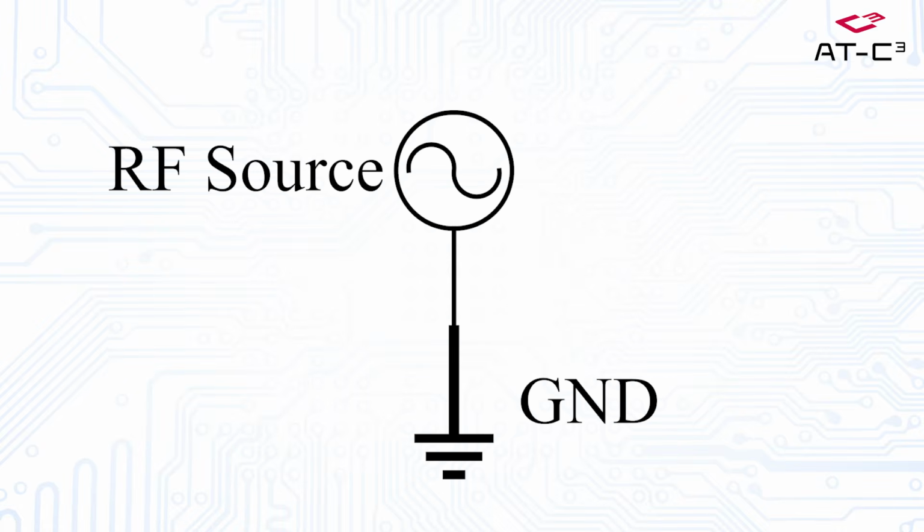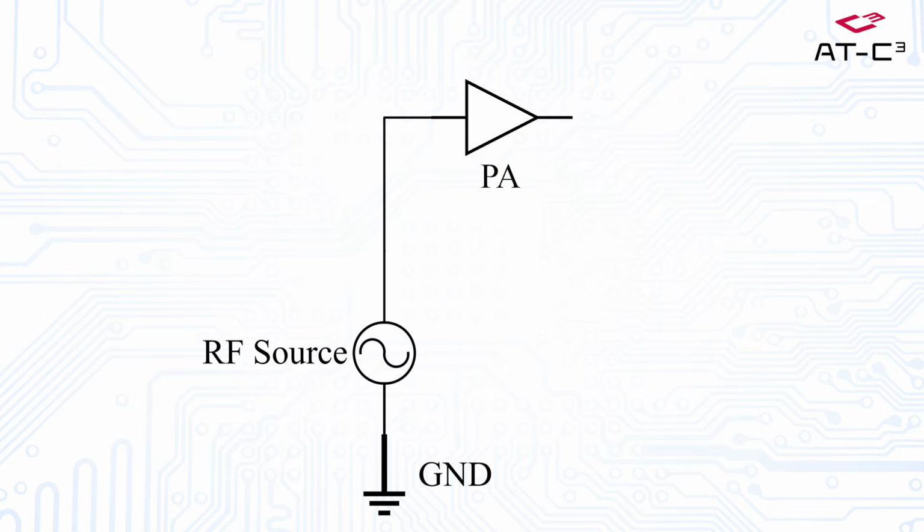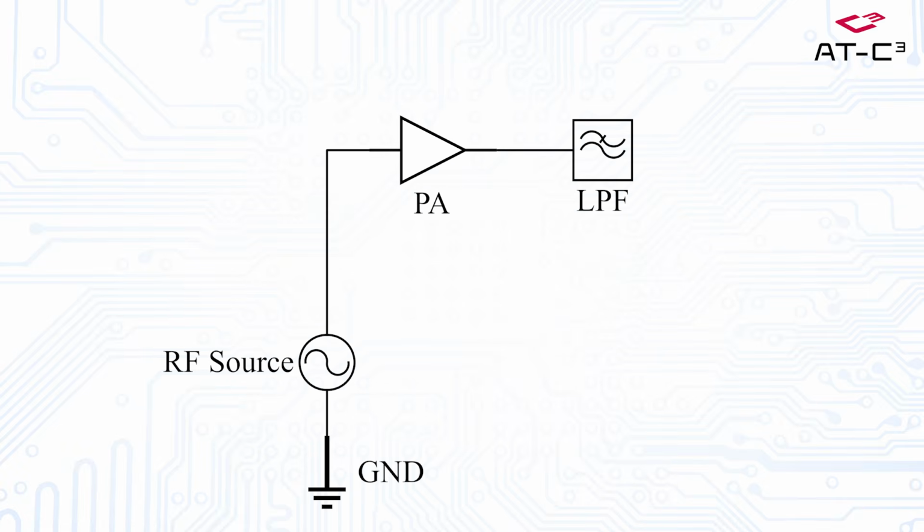We will need the signal generator at least to generate the fundamental signal. Then, to drive the DUT hard enough to produce measurable harmonics, we need a powerful fundamental signal. Typically, it is more than 20 dBm. Since a standard signal source lacks sufficient output, a power amplifier is required. Because the power amplifier is also a nonlinear device, it generates its own significant harmonics. We insert a low-pass filter immediately after the amplifier to reduce the harmonics coming from the source and the amplifier.